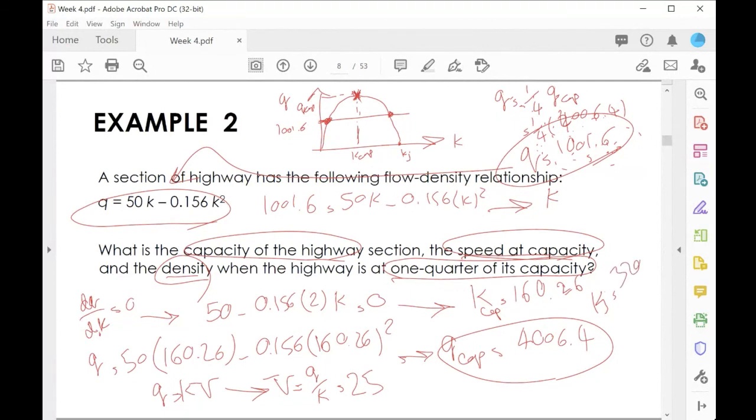And the second density we calculated as the root of that equation was 299. I just want to make sure it is lower than Kj to double check that the answer is correct. So in this case, one K is 21.47 and the other K is 299, while Kj is 320. So that's how we use the Greenshields model to calculate the speed and density at any traffic state.